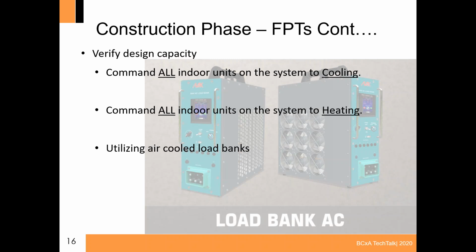Your space should be nice and cool by the time you do that. And so it has a nice, cooling load that it has to get rid of. And it may take 5 to 10 minutes for the system to switch over to heating, but just wait a little bit and then go through and take your temperature differentials again.